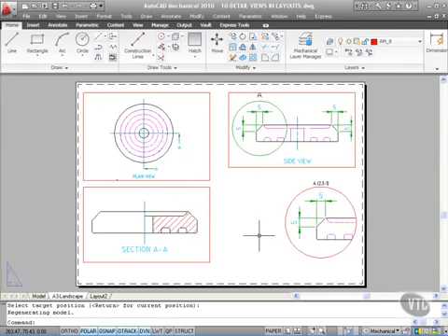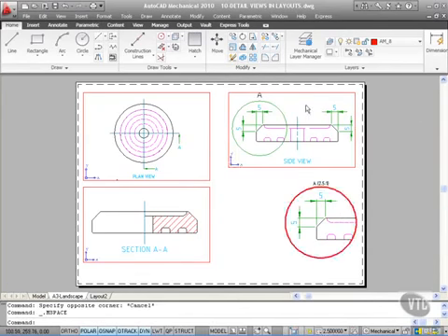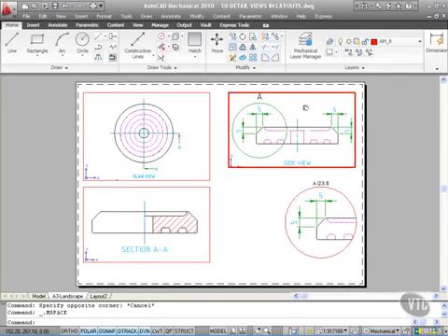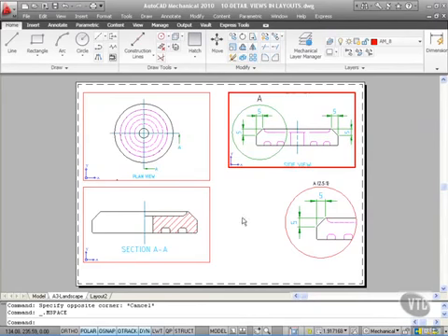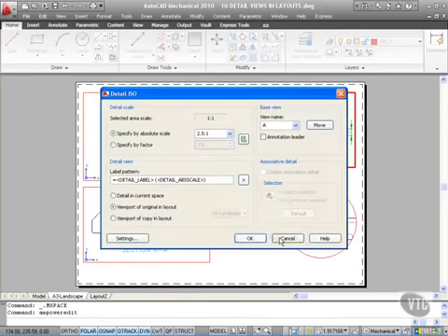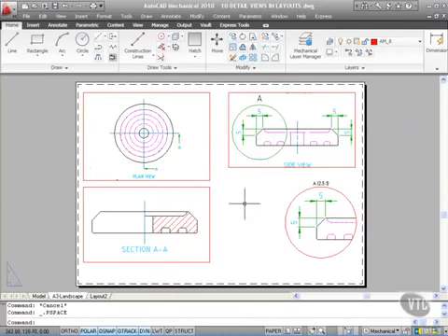And there's my view. Now I didn't actually put an annotation leader there, but look, I've now got a blown up view there, 2.5:1, view A, and there's view A there. So if I just double click in that viewport now, in here, and just pan down ever so slightly so that A actually fits, and there we go, that is absolutely perfect. If it doesn't fit perfectly, no problem. Just double click outside your viewport, cancel that for the moment, and hit escape there and double click.